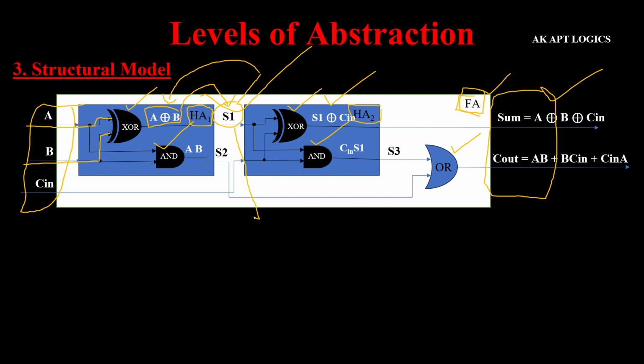It can't be either input or output, because it will be output from half adder 1 and input to the XOR gate of half adder 2. So we can't say whether it is an input or an output, and we can't declare it like that. The intermediate signal, we can't judge whether it is an input or output. There is no mode for it.